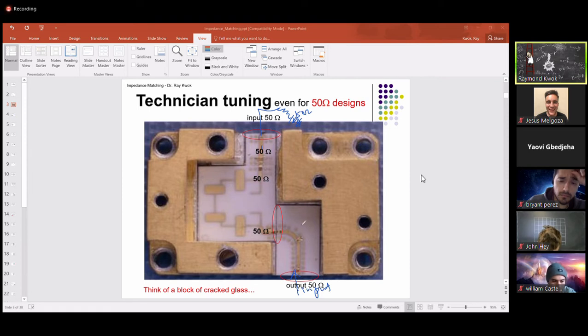All this piece of transmission line, all this piece of substrate, including my termination, whether this is port 2 on the network analyzer, is all considered as the load from looking at here.